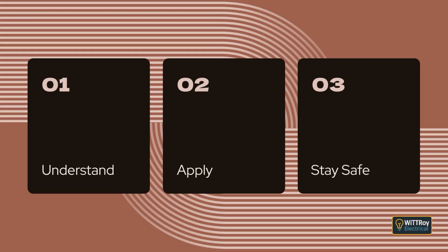Clause 3.11.4.3 Category B Mechanical protection. A Category B system requires additional mechanical protection. This must be placed not more than 75 mm above the cable, and must be at least 150 mm wide. The protection must also extend at least 40 mm beyond each side of the wiring system. This protection may be provided by precast slabs, cast-in-place concrete, continuous concrete cover, fibrous cement slabs, bricks, polymeric cover strips, or other materials that provide an equivalent degree of protection.